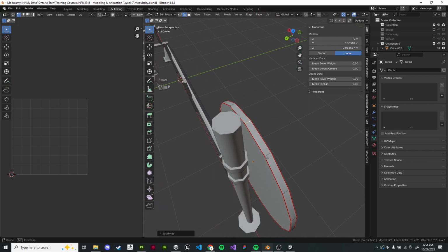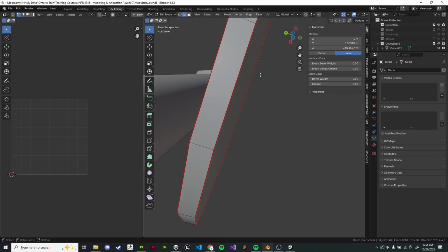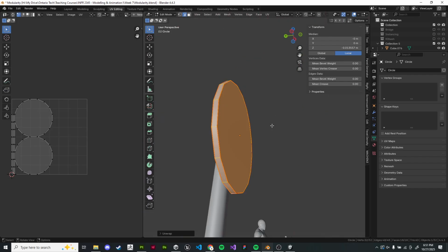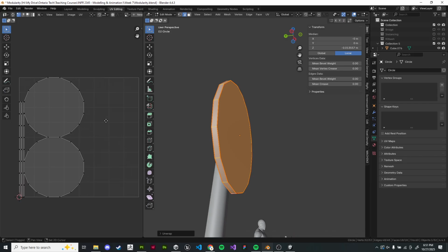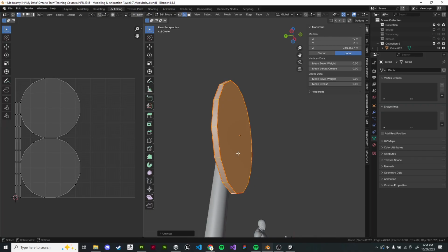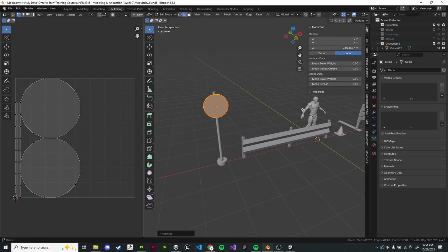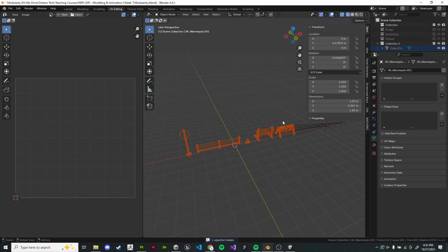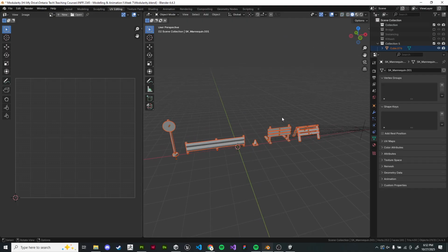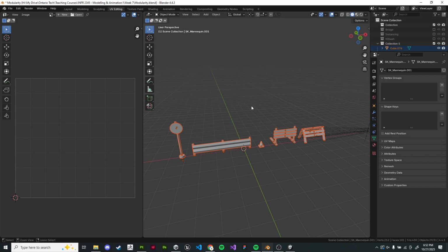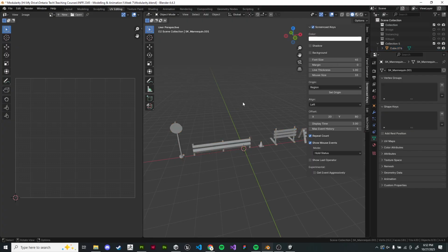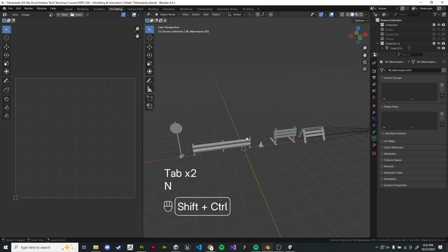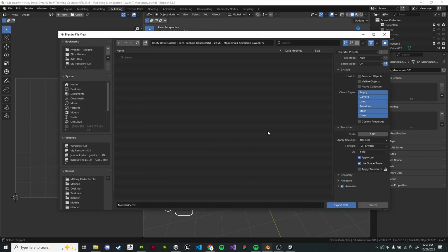So the sign here, just another circle. And I want to leave the sign like this. It's going to take up an entire texture map at a much lower resolution, but we need it to be unique, so we're going to leave it separate. And let's export all this now. So I did kind of highlight using that hotkey for exporting just to speed things up. So if I Control Alt Shift F, I can export as FBX here.